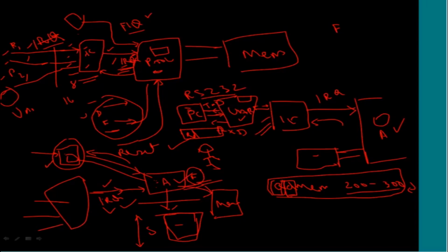So it will read these characters first and put them in a buffer, a command buffer, and then check whether it is a carriage return or not. Maybe 0A or 0D. If you remember, these two are carriage return and line feed, so one of these may be a terminator to say that the complete command is given. Based on that, the first level interrupt handler can inform the second level handler that a complete command is received. Now the second level handler can come into play.